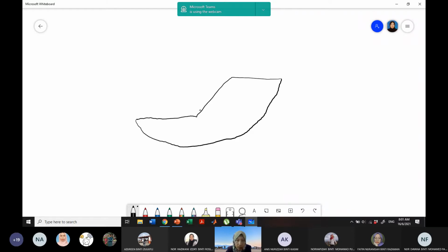So let's say we have a slope here with a certain height and with a certain angle, and this is the circular arc. First of all, what we want to say on that part is you have to identify which method you are going to analyze, whether you have the Swedish procedure or the method of slices. So for this one, we might use the method of slices for our slope stability analysis.